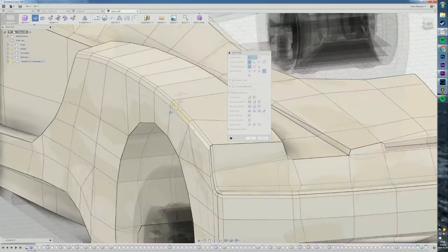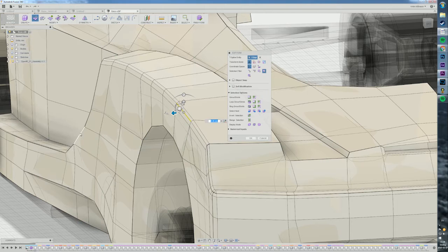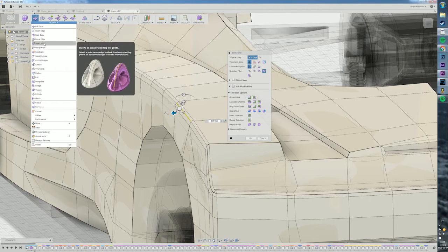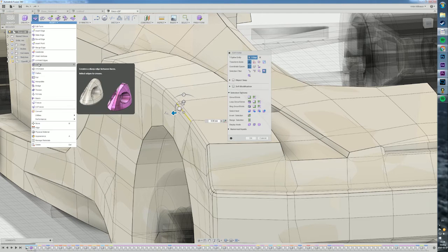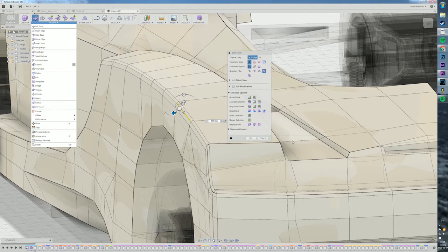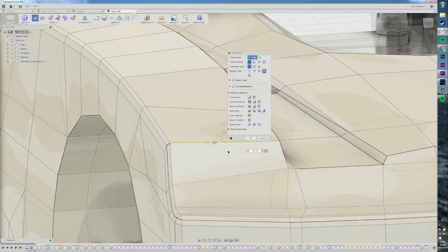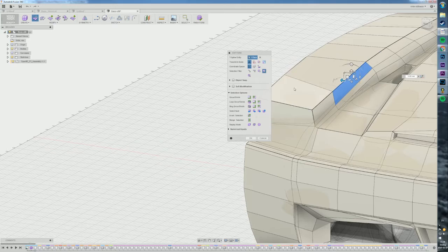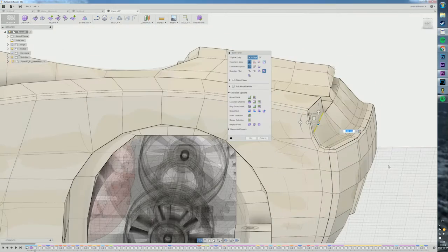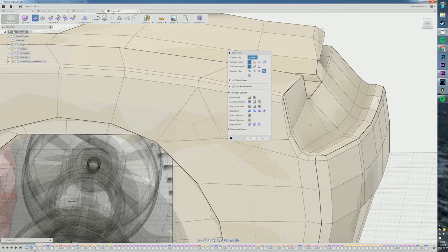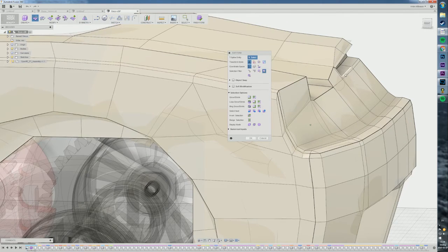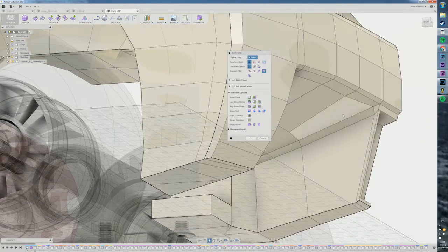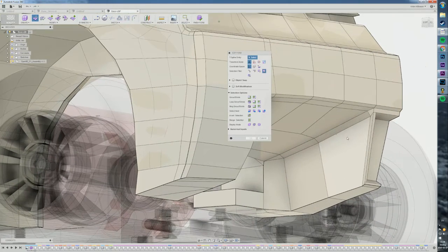There's two ways of adding a sharp edge. You can either do something that is called modify crease edge. You can see here it creates a sharp edge between faces. That's really good. I can do that in some places. For example here, these thicker black lines are sharper compared to, let's say, this line, which is a flow. So you will see here now that we have sharp lines. It's to define, let's say, a vehicle line here, but up here I don't have that, and neither do I have it over there or over here. So these motions here will be smoother.